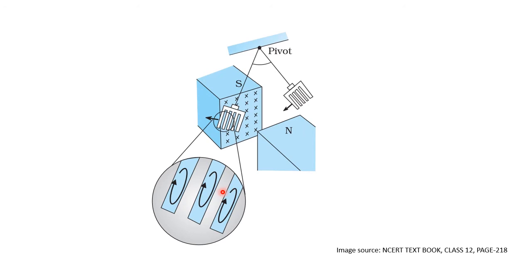The reason for the clockwise direction is that the magnetic flux is going inward, for suppose, and it doesn't like to decrease, so it tries to develop magnetic flux in the same direction, inward. To develop the magnetic field inward, apply the right hand grip rule. Curl the fingers inward to this conductor, then your thumb indicates the direction of clockwise. That is why the current is in the clockwise direction.